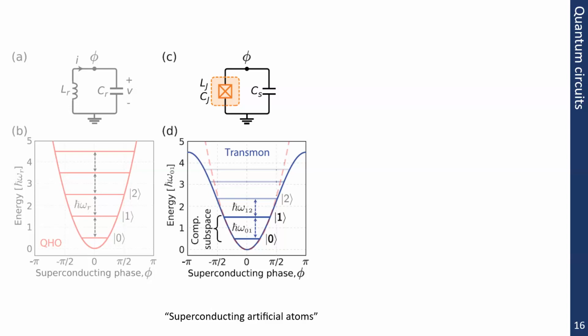If we design the geometry and materials of these Josephson junctions of the circuits, we can design the operation frequency, and this is very useful, especially because natural atoms, which are also used in quantum computing, by the way, have transitions that are fixed or largely fixed. Here we can design this atom, this transition, at our will.